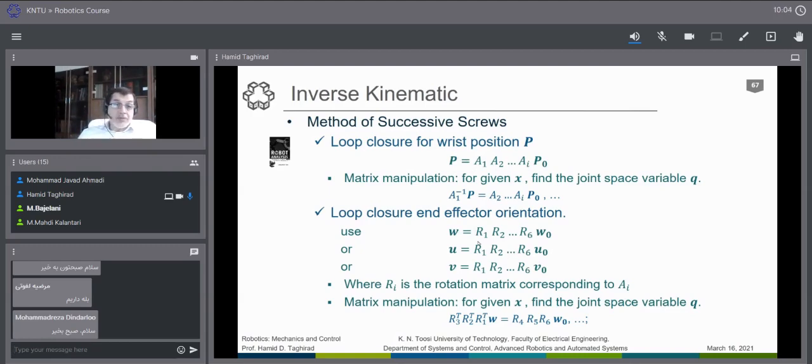You can find the UVW with a reference frame quite easily, and these UVW are the orientation of the target point that depends on the orientation of the end effector and on the task space variables which are given in the inverse kinematic. Again, which one to use is quite dependent on the problem, but you find the one which gives you the simplest variation here.